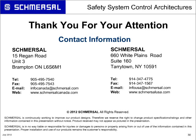Because part of a locking function, when you have residual motion such as rotary, maybe it takes the machine 10, 20, 30 seconds to wind down before it comes to a stop. When you have that and you need that door to be locked during that process, you're either monitoring via speed, stop motion, back EMF, encoder feedback, or just simply timing because it's consistent, a safety timer, that you're keeping that door locked for safety reasons. In cases like that, the lock needs to be monitored.